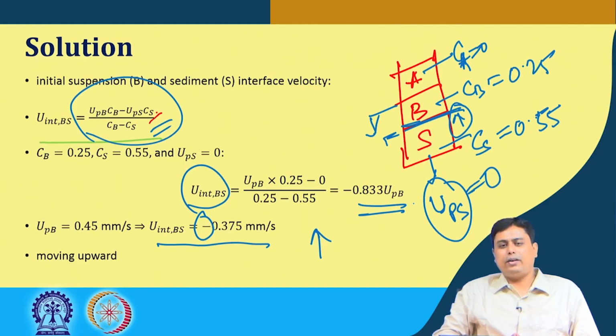and then we verify that by calculation of the particle Reynolds number. If it is indeed in that region, then we can go ahead with the value of n for the Stokes law region. Otherwise, we have to use the appropriate expression in the other regions to calculate UT, that is the terminal velocity for a single particle. Once we find that, we also know by that value what is the particle Reynolds number. We use the appropriate expression of n, and then we find out the hindered settling rate.